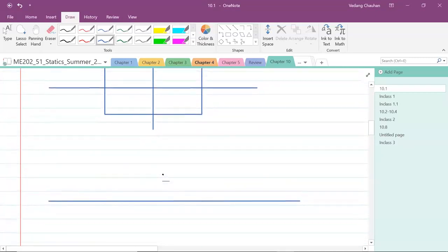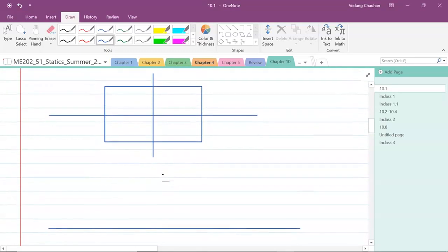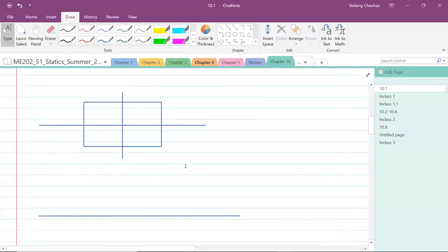But what if we try to bend the shape relative to an axis which is shown here, and that axis does not pass through the centroid? So the centroid is here, this is still B, this is still H height, this is x-axis and this is x dash. So how can we calculate? Those two axes are parallel and the distance between them is d.